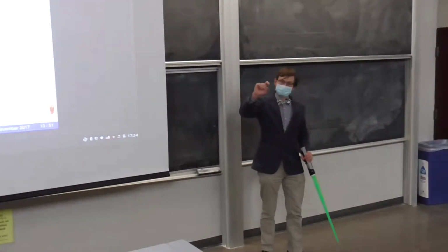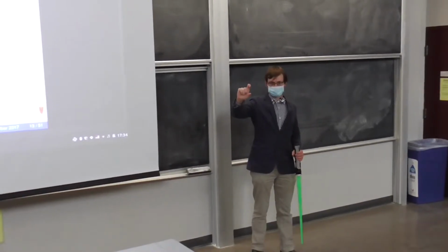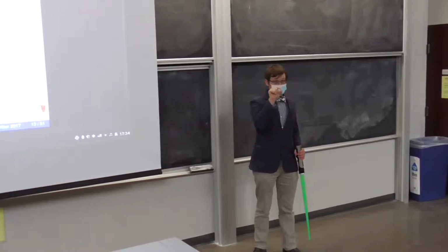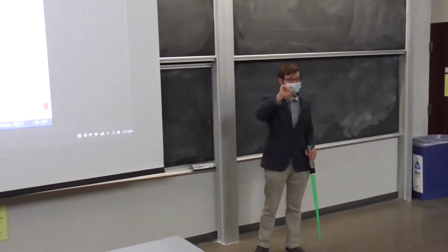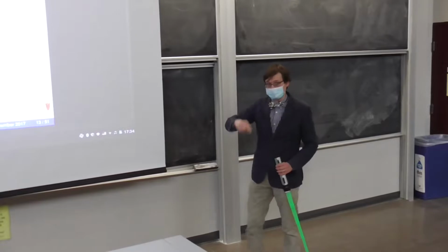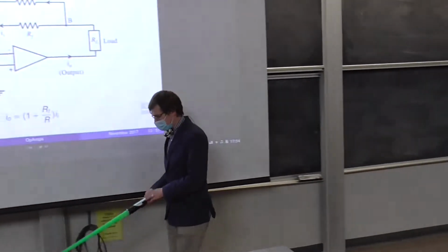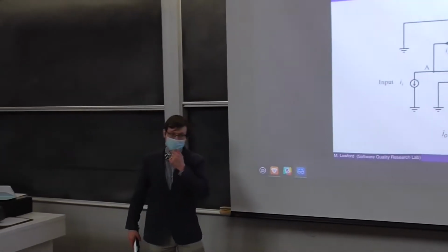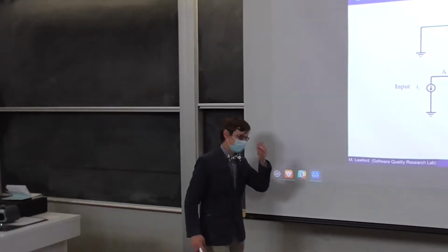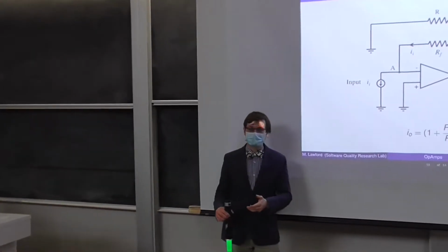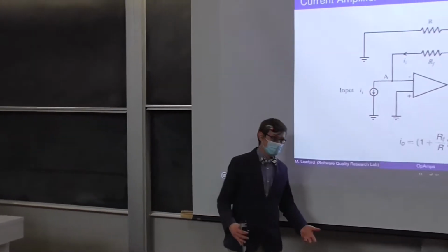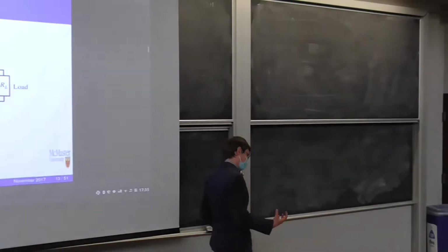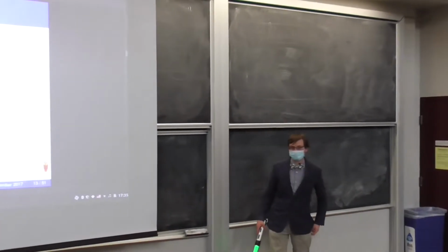One, the information contained in that signal might be in such small increments, such small fractions of a volt, that you can't really pick it up with your analog to digital conversion, right? So this would be an application where you need amplification. You need to amplify the signal.